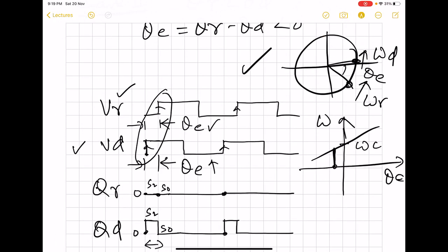So what we see in this case, negative voltage will be fed to the VCO. That will then reduce the output frequency. So this is the output frequency of the VCO. When omega naught reduces, this will imply that omega d reduces. That will imply that omega d rotates with a slower velocity. And in that case, omega r will be able to reduce this phase error between the two signals.